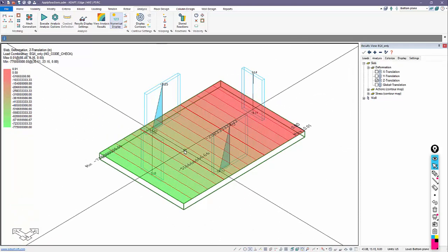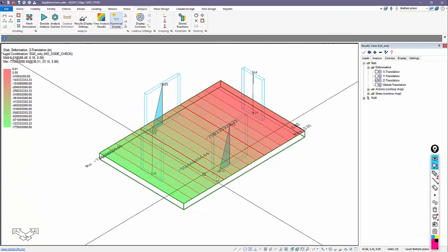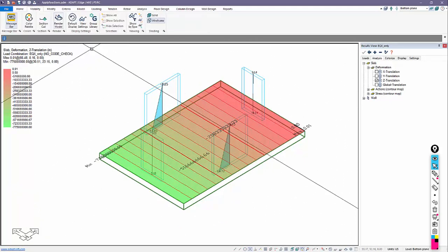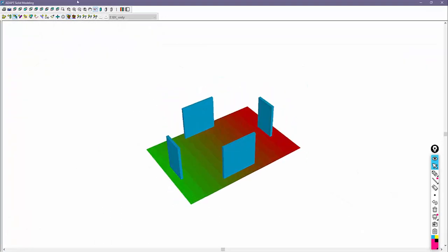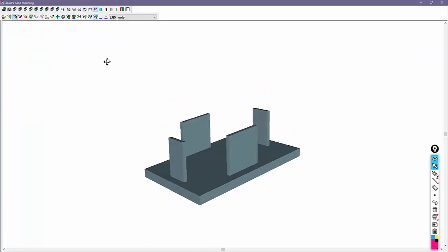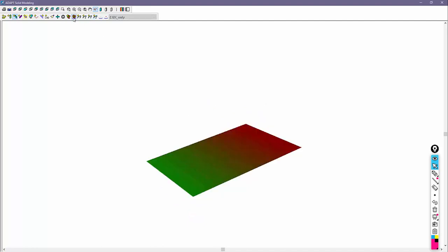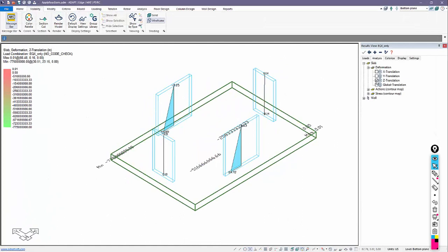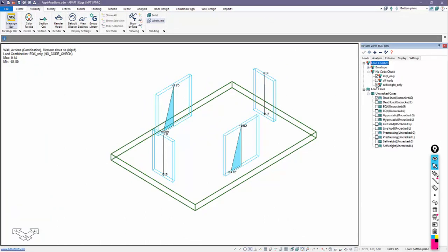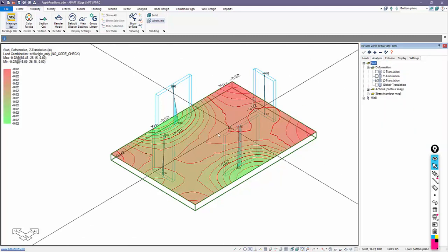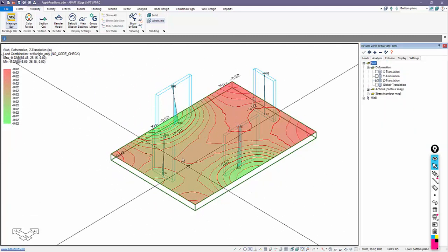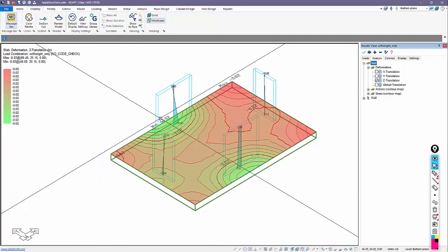One way to see this would be to go, once I select the deflection view, to visibility, render model, and using this selection here, you can see renderings or warpings of the model. So this is completely going off the page because the value is so high. If we go back and look at the deflection, for example, for self-weight, and I look at the vertical deflection here, you can see the range of vertical deflection. This is much more reasonable compared to the EQX deflection.